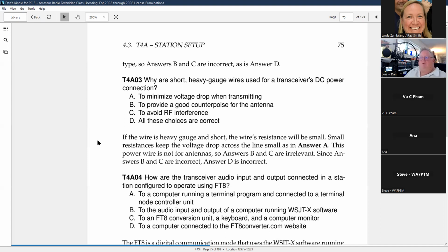So to let more through, we use a bigger straw. We use heavier gauge wire because we're going to run off amperage, which is the volume of the electricity. We need heavier gauge wire. Shorter is better, longer we have loss. So short, heavy minimizes the voltage drop. If it's too skinny, it just doesn't get through, the voltage falls off.